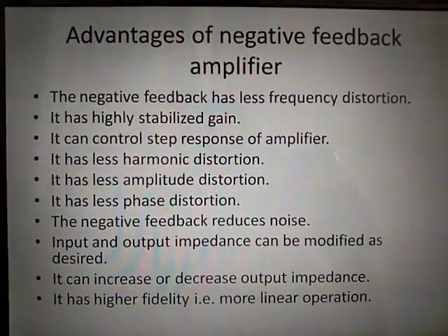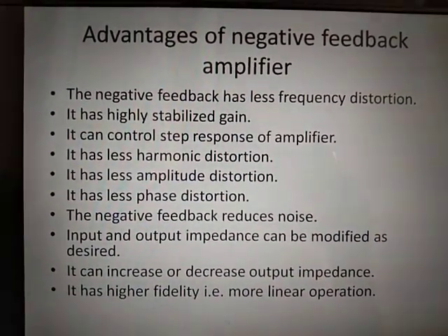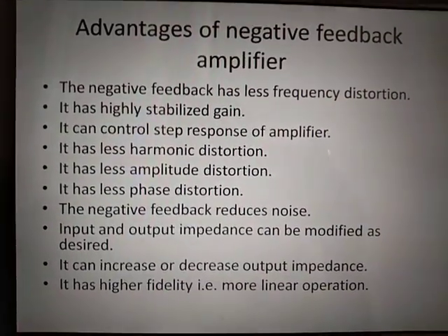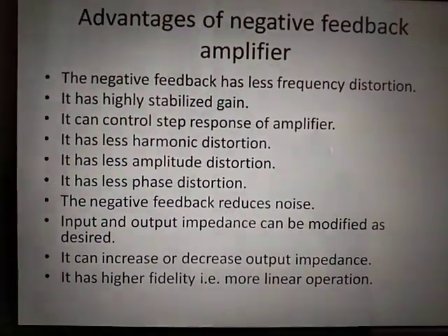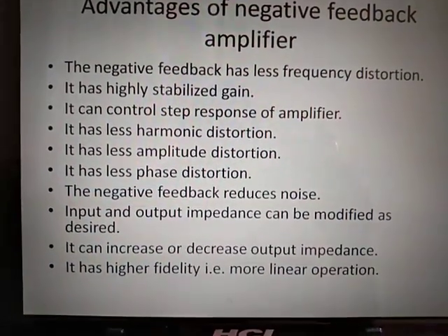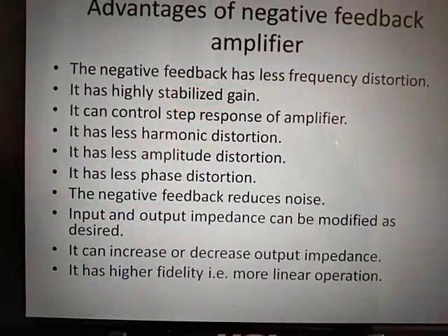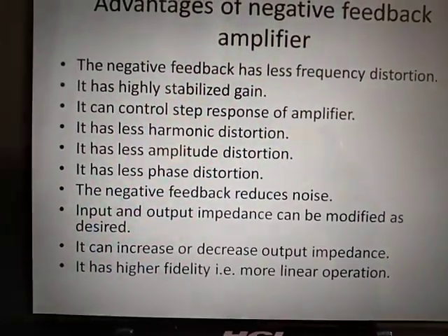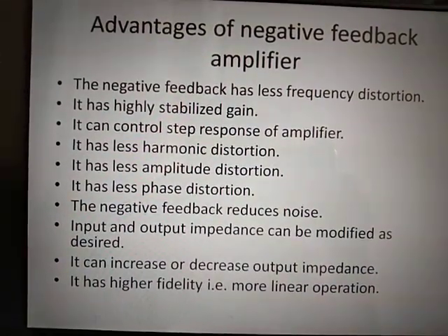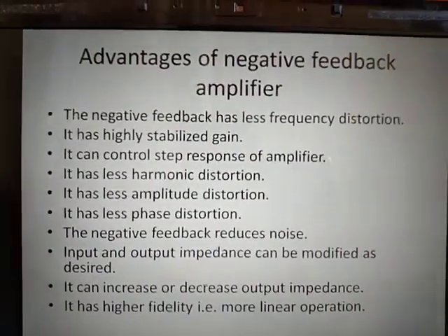The next is important. What are the advantages of using a negative feedback amplifier? There are various advantages here. The negative feedback has less frequency distortion. It has highly stable gain. It can control the step response of the amplifier. It has less harmonic distortion, amplitude distortion, and phase distortion. It is controlling the very small signal. And the negative feedback reduces the noise. Input and output impedance can be modified as desired. It can increase or decrease the output impedance. It has higher fidelity, that is, more linear operation.